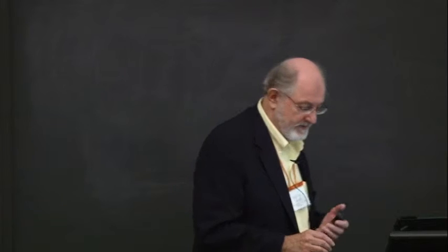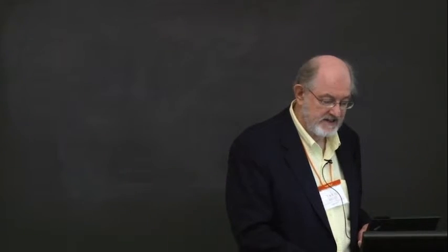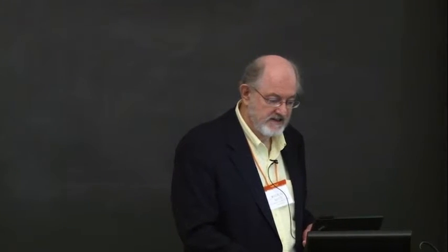Okay. Sure. Are there any modifications that need to be made to the engine setup to run this? So run at low speed and run at high BMEP, and you're going to get it. You saw that. For the engine itself, it is knocking so many times. I'm just wondering, has there been any damage? Oh, absolutely. People have destroyed engines with super knock. That's why it's such a problem.